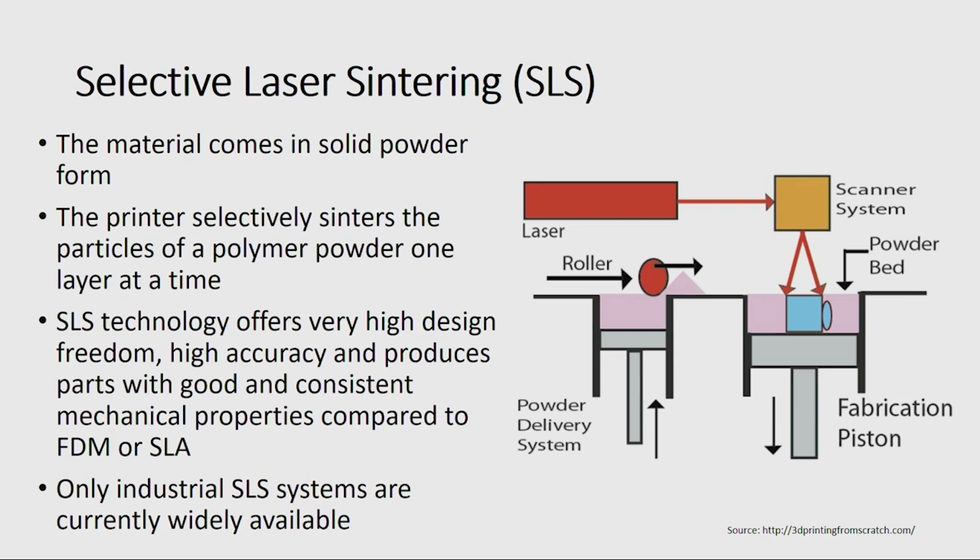So here the material from the reservoir is transferred to the build volume, then the laser is pointed and the material is heated, and the material which is exposed to the laser will be sintered, and the material will adhere together.